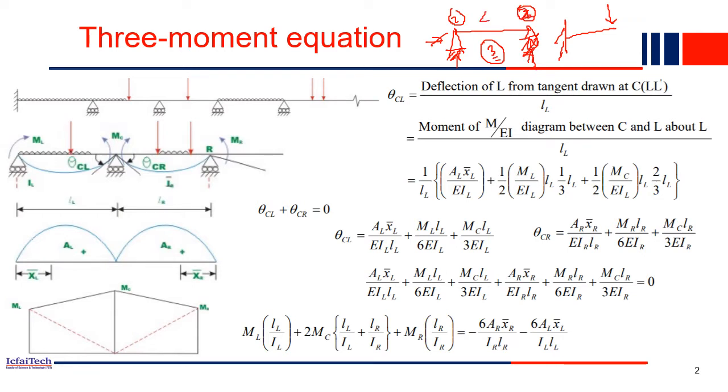So in total you now have four unknowns, and you have three equilibrium equations, right? So using the equilibrium equations we can calculate at most three unknowns, but one more unknown we still have to compute, right? So using the normal method we can't solve indeterminate structures. So for this beam, if this end is hinge and this end is also hinge, then we call it an indeterminate beam of degree of indeterminacy 1, because three unknowns we can calculate but one unknown we cannot calculate. So it is a beam with degree 1 indeterminacy.